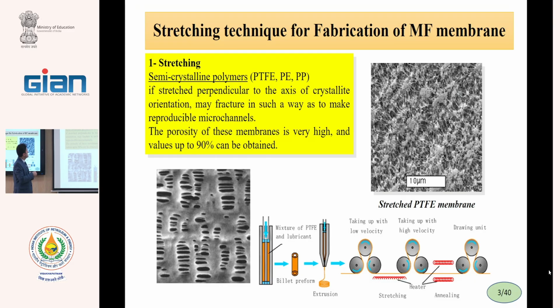The porosity is very high, the flux is very high, the pore size is big. Therefore, these membranes are mostly microfiltration. We cannot produce nanofiltration with this method. In this method, we have a big pore size.